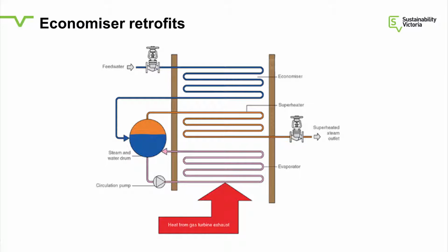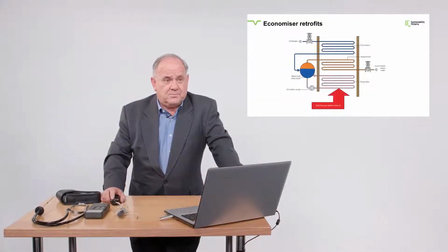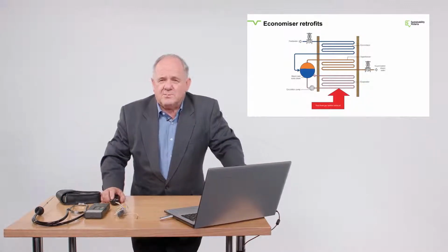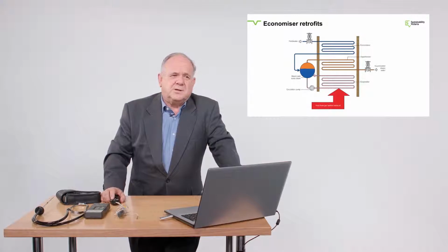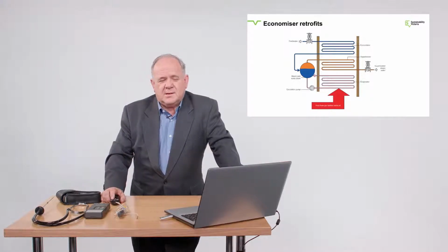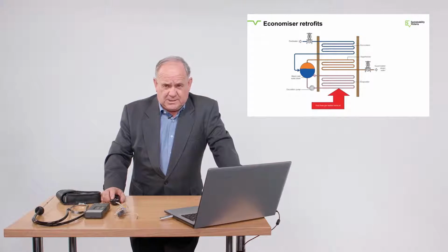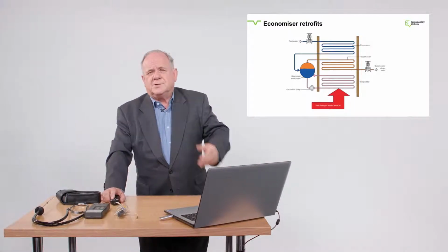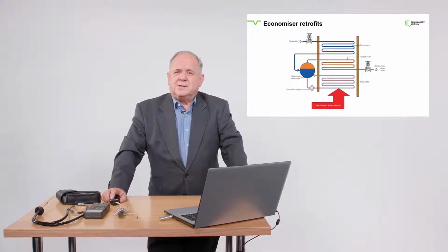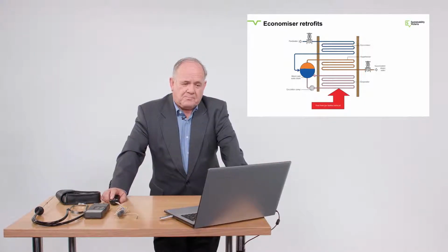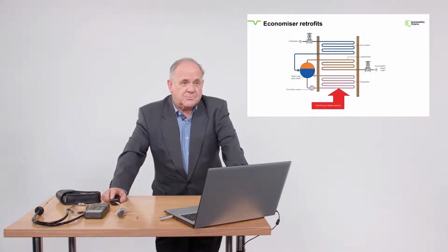above 10 megawatts capacity, have these virtually as a mandatory thing because the payback's very good on them. So, payback on a new boiler, if you were to put an economiser in, might be 1 year or less. On an existing boiler, if you retrofit it, you can get paybacks certainly of 2 years, a bit over 2 years. And that's using stainless steel heat exchangers these days so that you don't have corrosion. The economisers that are being built nowadays are a lot more robust and last quite well. So that's certainly worth considering if you haven't got economisers on your boiler.